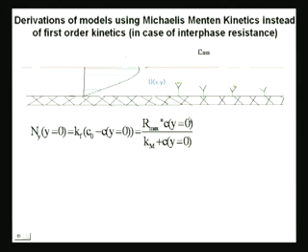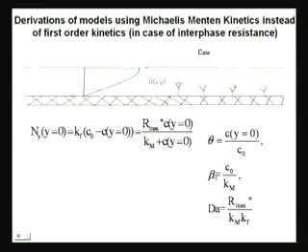Now, what was the reaction previously? Previously we looked at the first order reaction, okay, which means that it was some k times C, k s times C. Now, we are looking at Michaelis Menten kinetics, which is nonlinear. So, before we actually try and solve this, we make the system dimensionless, and this is really important in this case, it is not out of fancy that we do it.